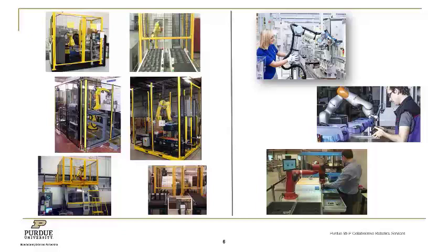I'm often asked by folks who attend my in-person presentations on cobots, what does it feel like to get accidentally hit by a cobot arm? And the answer depends on the combination of the speed the robot arm is moving, how much weight it's carrying, and what the specific settings are on those force and power limiting sensors. But when a unit is properly configured, it feels like you're walking down a hallway and someone is walking in the opposite direction and you accidentally bump shoulders with them. So you notice it, but it doesn't really hurt you.